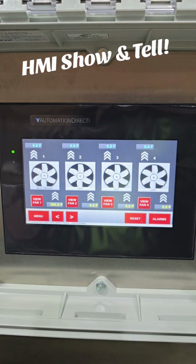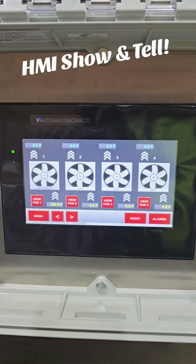So the navigation buttons. One thing that always kind of annoys me a little bit with some SCADA developers is sometimes they add these buttons in, but they're not very consistent about where those buttons are on the screen. More or less, they're in the same spot, but some people tend to forget to make sure that exactly X and Y where the button is is consistent across all pages. So sometimes when you bounce between pages, especially if they're identical pages, you'll notice that the buttons kind of shuffle around a little bit. So that's always something to keep in mind whenever you're doing HMIs.